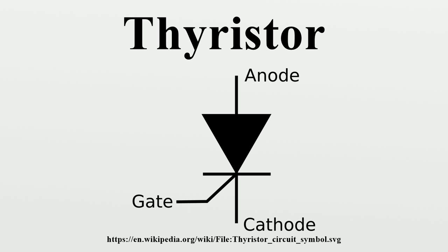The precise switching point was determined by the load on the DC output supply, as well as AC input fluctuations. Thyristors have been used for decades as lighting dimmers in television, motion pictures, and theater, where they replaced inferior technologies such as autotransformers and rheostats. They have also been used in photography as a critical part of flashes.